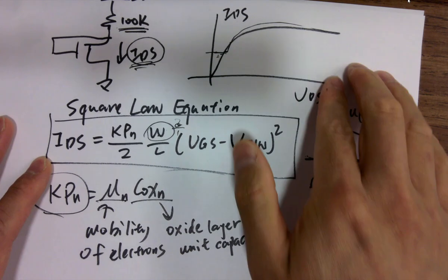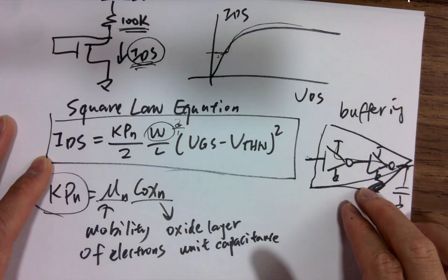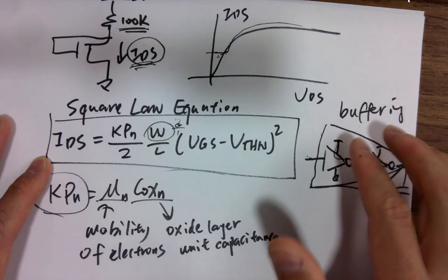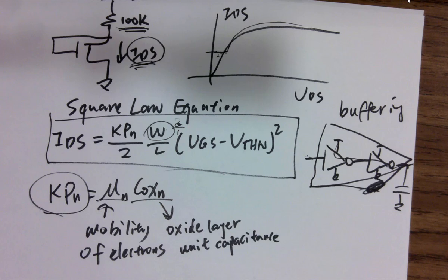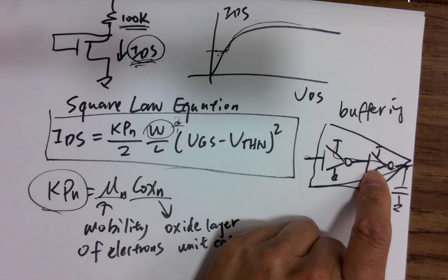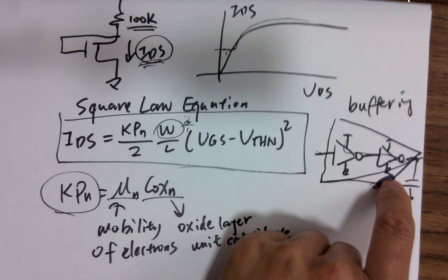Since you have more connections to the VDD and ground, whenever you are discharging the cap or charging the cap using VDD, you just have more connections to the sources. It's dumping in or pumping out more current from the capacitor. It's actually increasing the driving capacity of the circuit. That's why we are buffering, because of this.